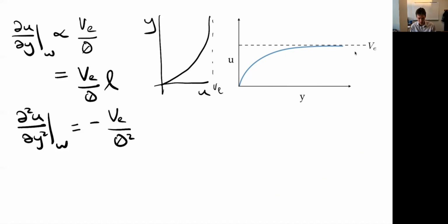So the boundary layer does not have to have negative curvature. That's just going to be the typical case, but it could have positive curvature at the wall. I remember the negative curvature is the frowny face, looking down, but it could also have a positive curvature at the wall. It could, for example, look more like this, and then come up, which in this case would look something more like this. But we can see that as that curvature becomes more positive, it's flattening out here at the wall.